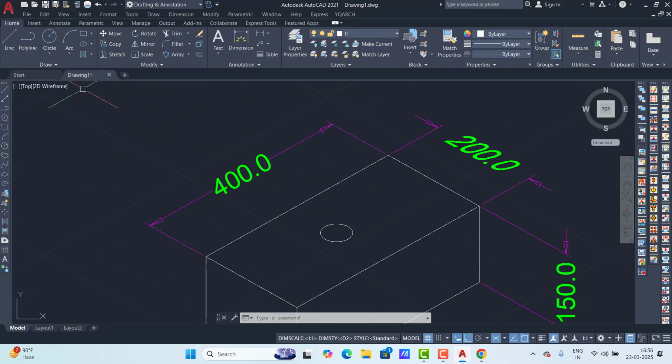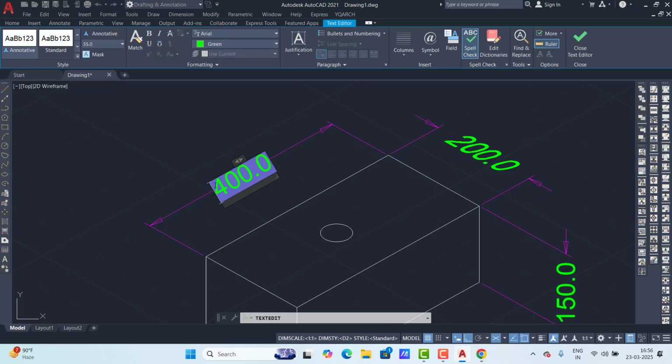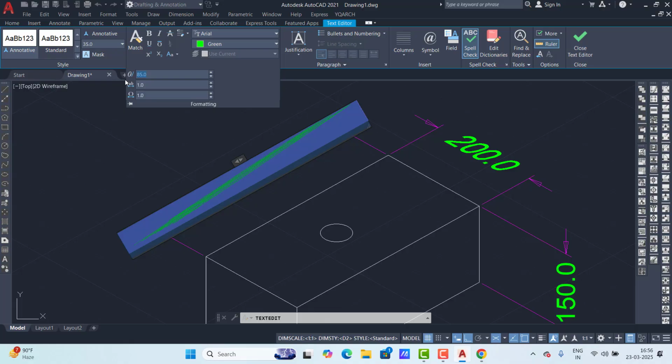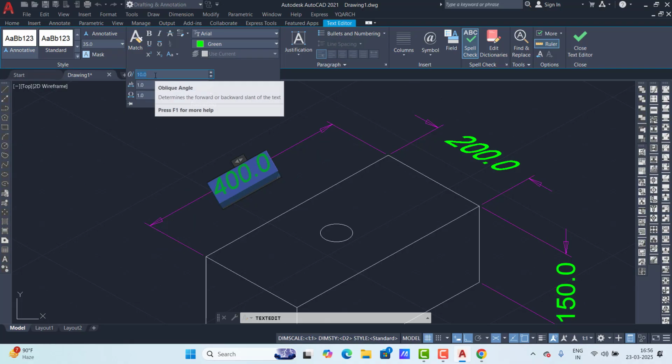Okay. Same on the downside we have to make, but here 29 and 15.7, and the small circle radius comes 4. So just C enter, again create here 29, again C enter, center, that is 15.7, C enter, again the small hole, type 4 radius, polar array, select this one, enter, give the center here, enter, type 18. Okay, that is the complete number.